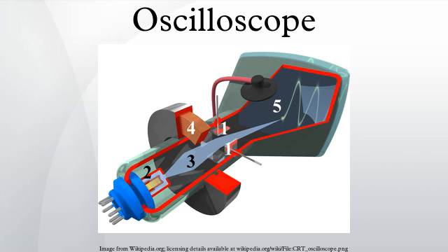As of 2007, a 350 MHz bandwidth, 2.5 gigasamples per second, dual-channel digital storage scope costs about $7,000 new. On the lowest end, an inexpensive hobby-grade single-channel DSO can now be purchased for under $90 as of June 2011. These often have limited bandwidth and other facilities, but fulfill the basic functions of an oscilloscope. Software: many oscilloscopes today provide one or more external interfaces to allow remote instrument control by external software. These interfaces include GPIB, Ethernet, serial port, and USB.